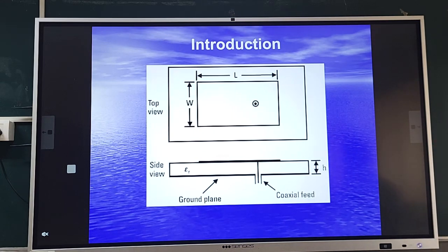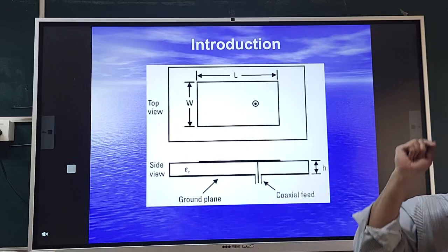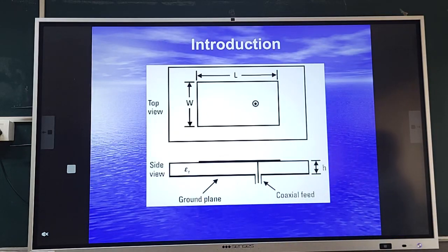Whereas against that, if I use a very efficient microwave substrate, because remember, the choice of substrate not just depends upon the application, it all depends upon the frequency of use. If I am designing my antenna around 900 megahertz, FR4 may work well. But if I am designing my antenna at 10 gigahertz, then definitely FR4 is not a good choice. Why? Although it is cheap, it is a very lossy substrate.